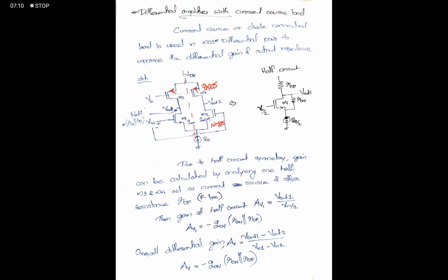Here the P MOSFETs also must satisfy that condition. So we are choosing M1, M2 such that the transconductance parameter is Gmn, and here the transconductance parameter is Gmp, and the resistance here is R0n for the N type MOSFET, and here it is R0p. That's all. So the analysis is very simple, because it satisfies the half circuit symmetry, we will consider only one half, and we write an equivalent half circuit of that differential pair.